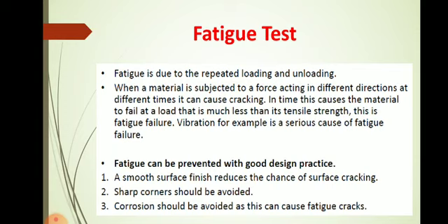So if there is a smooth surface finish and fewer cracks over the surface, there is less chance of surface cracking due to fatigue. Sharp corners should be avoided to avoid fatigue failure. Corrosion should also be avoided, as it can cause fatigue cracks. These are things you can do for avoiding fatigue failure.